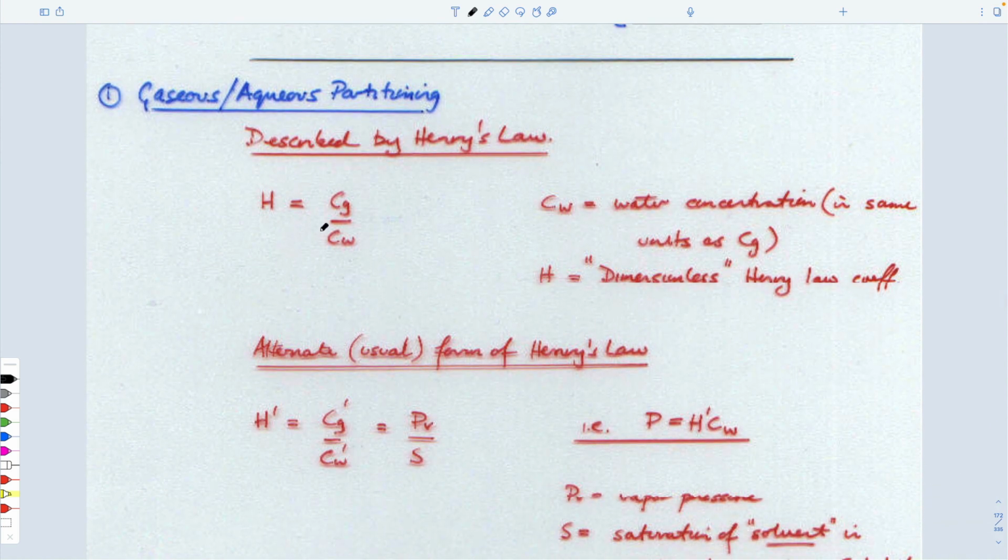One appropriate way to figure that out would be to evaluate exactly what the equilibrium concentration in the air-filled portions, the concentration of gas, is relative to the aqueous concentration. We could define those by what I'll call a non-dimensional Henry's coefficient, because if these are both units of concentration, mass per unit volume, then the ratio of them has no units.